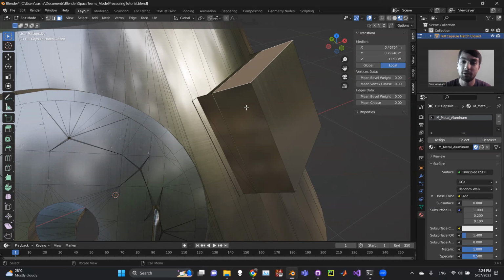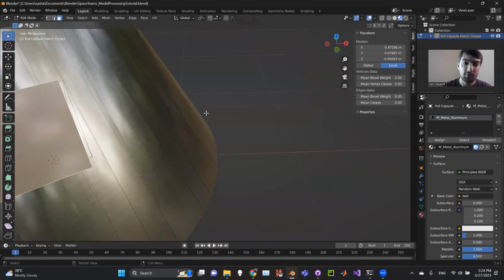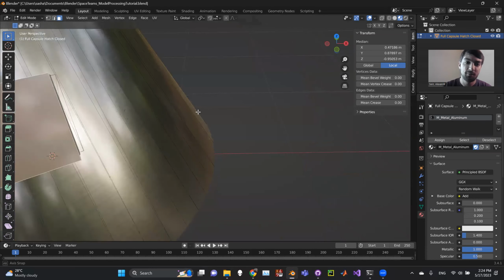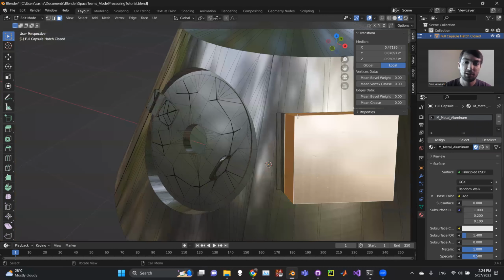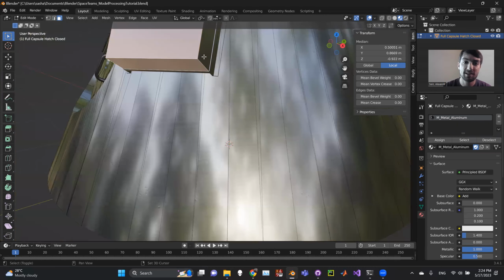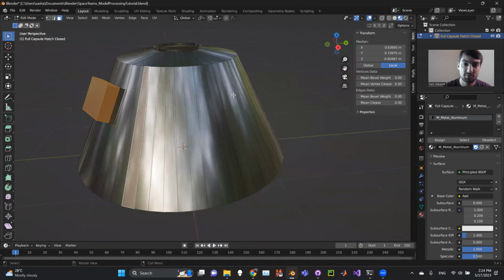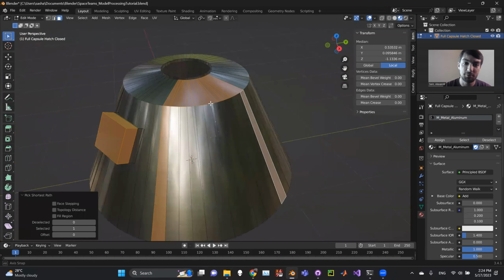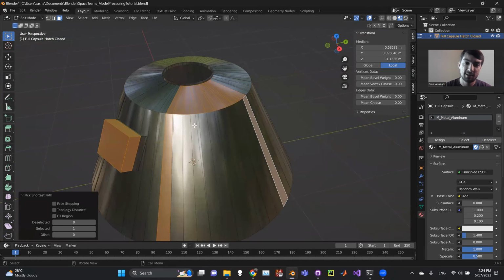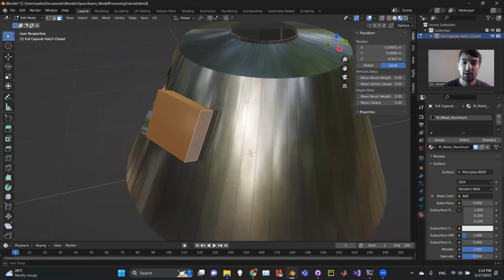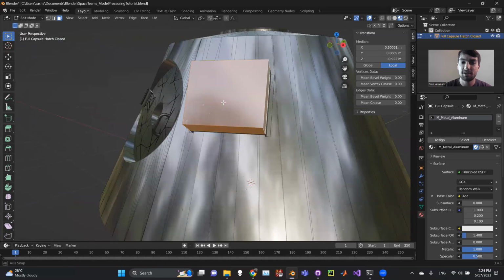And to do that, you either hold Shift and then left click like that. Or you can also control click as we did before with faces. Let's say I want to select from this one all the way to somewhere over here. I'm going to control left click and I'll select what it thinks is the shortest path, which sometimes is very interesting. So I'm just going to undo that a little bit. But let's say we want to select this box.